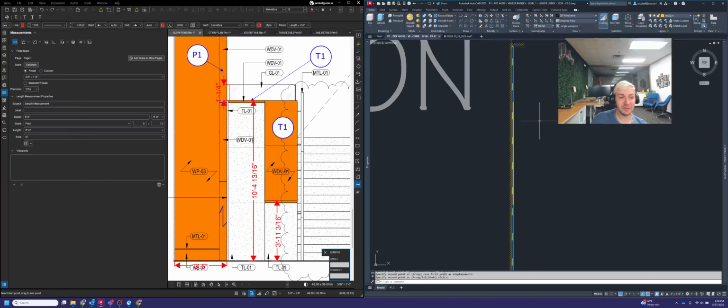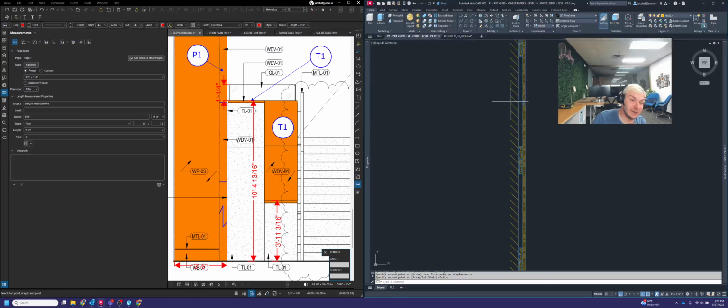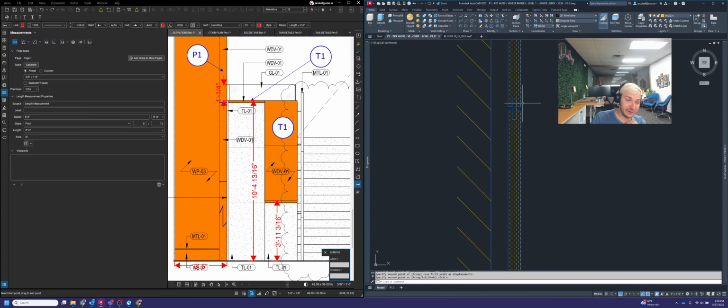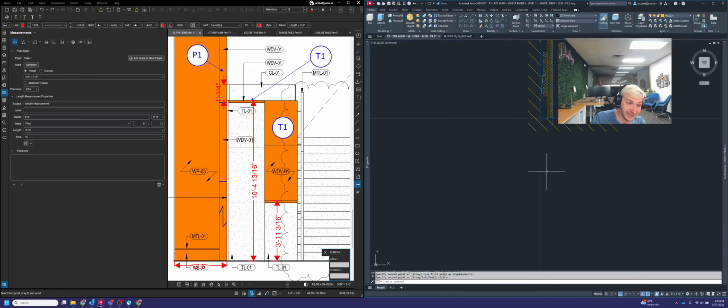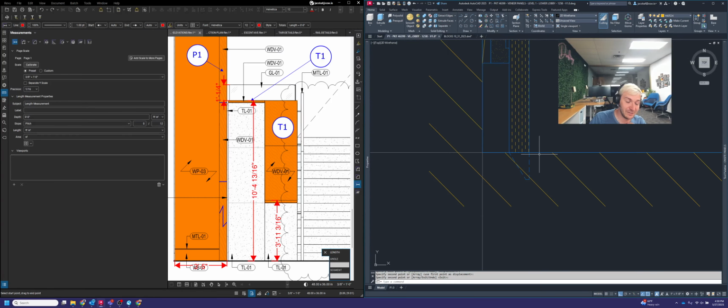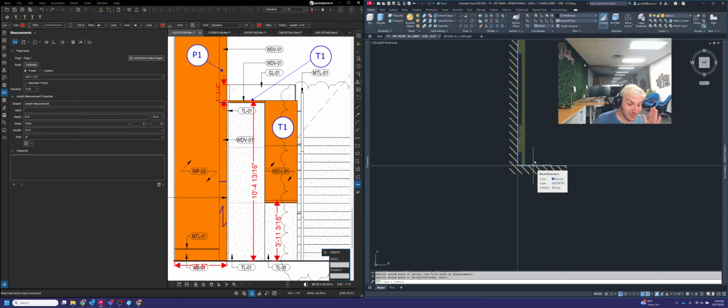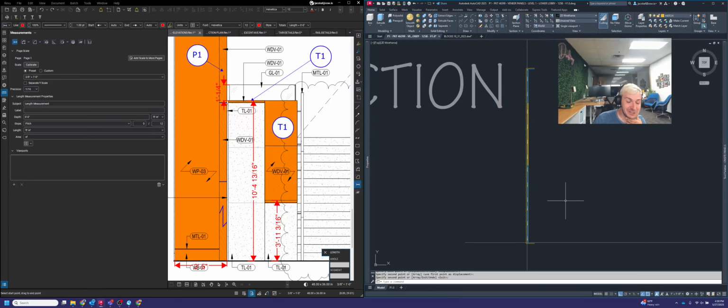We got our fold up reveal at the top, 3/4 inch tall, 1/4 inch spline reveals in between panels, panel intersections, and then we got our 1 inch scribe to the floor. Sorry, got my vocab mixed up there. It's near the end of the day. So 1 inch scribe to the floor there, and our wall panel cleats there. Okay, so that's our section view.